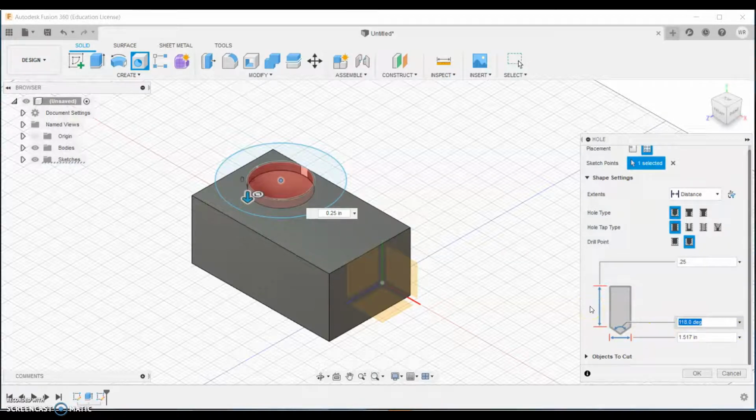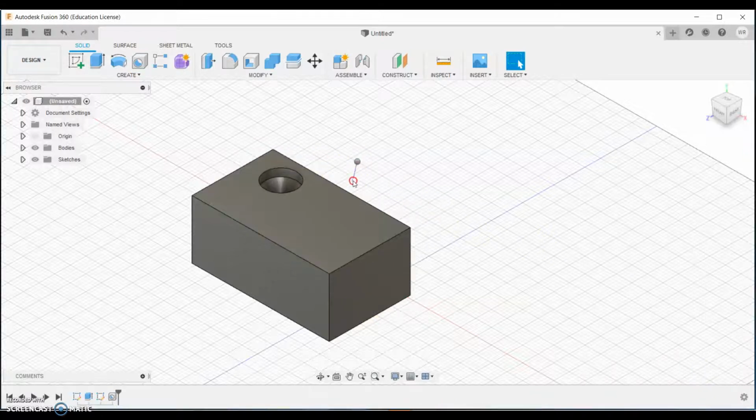Depending on how you're going to go, that could be a 90-degree angle, that could be 100 and whatever, it could be 30 degrees, etc. And then how wide the hole is. The hole is obviously too wide for the object right now. So if I wanted to make that like 1 instead, okay, now I have my hole.